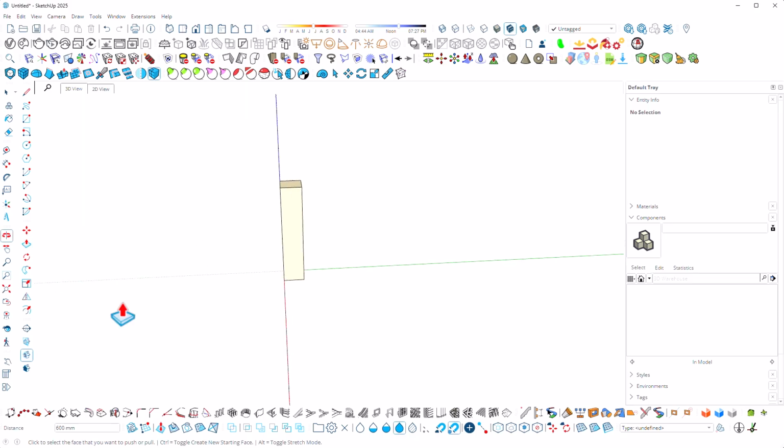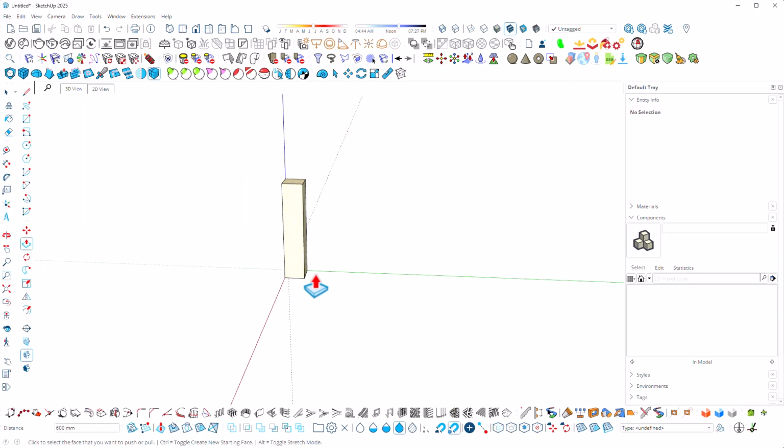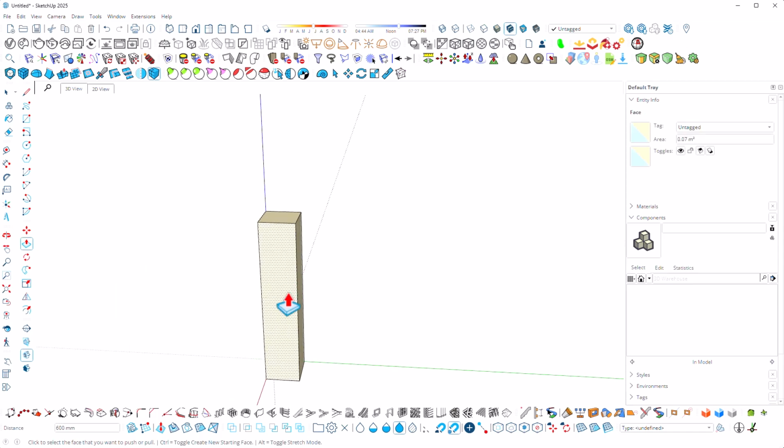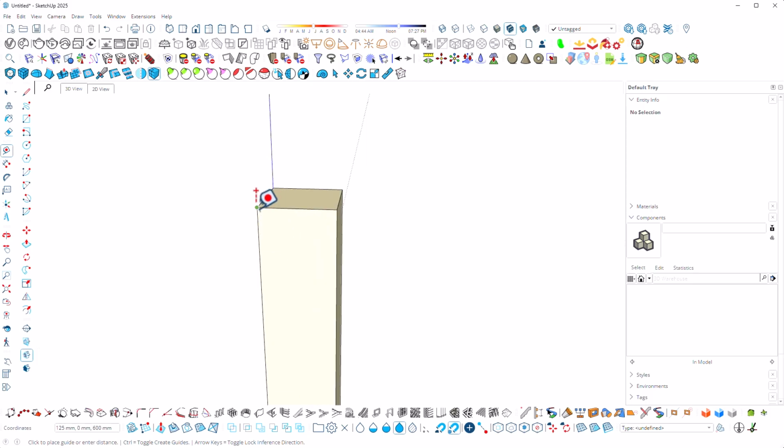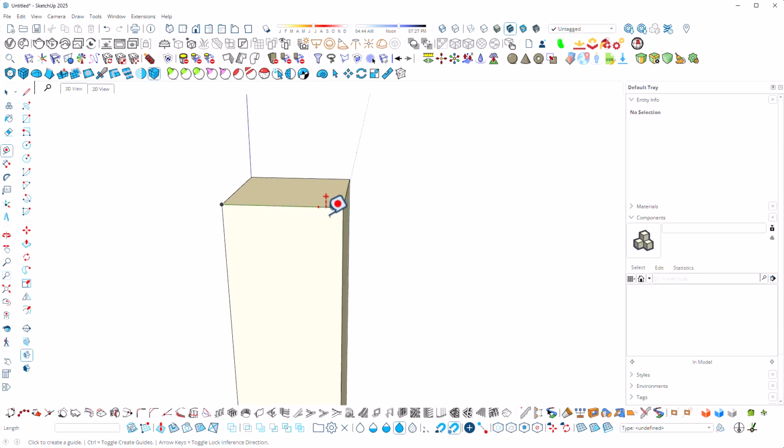Now we've got what resembles a timber sort of member, but there are a few more things to do to this to make it a pile. We need to create a chamfer, get rid of this corner, so that it will accept earthquake bracing, up the bearer, etc. The bearer that's going to be planted on here is 100 by 100 bearer. So what we'll do to delete this corner is grab our tape measure tool, click on that, zoom in a bit, select this corner, come across 100, you can type in 100 mil. That'll give us a node.